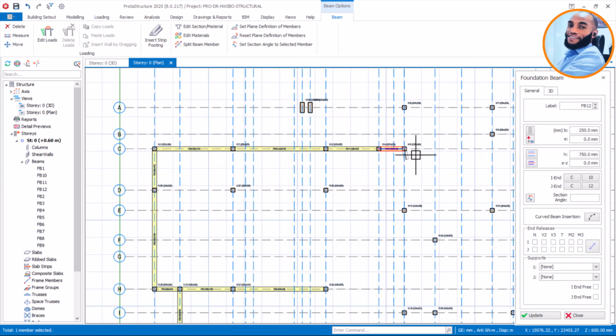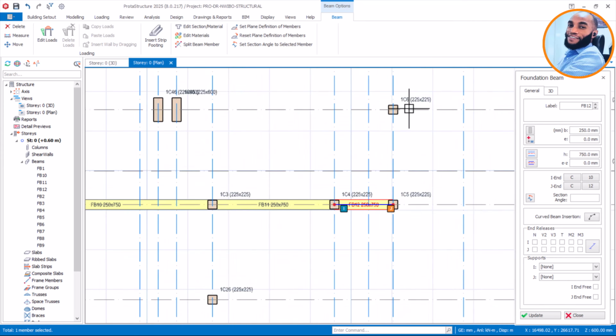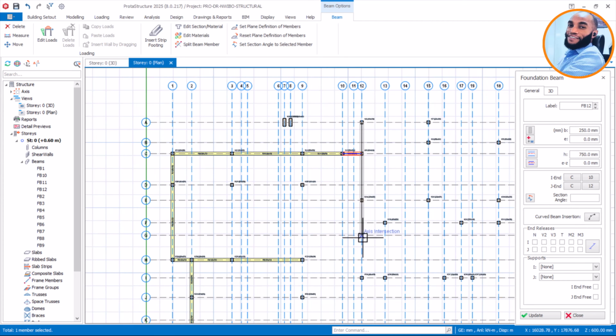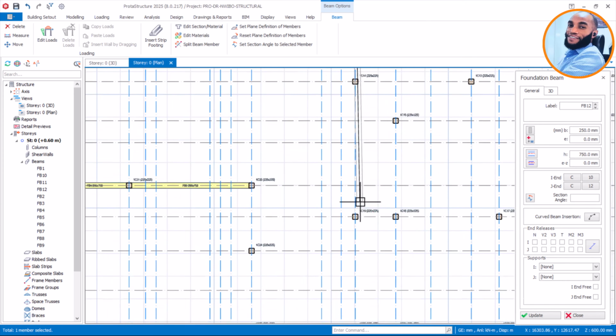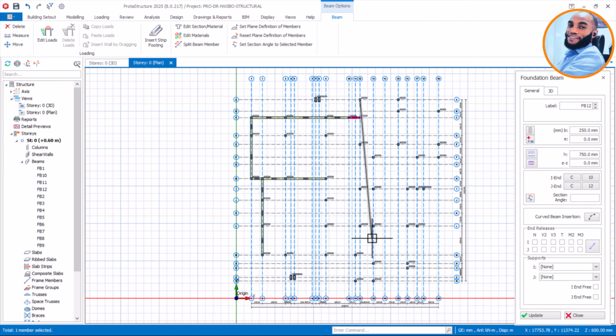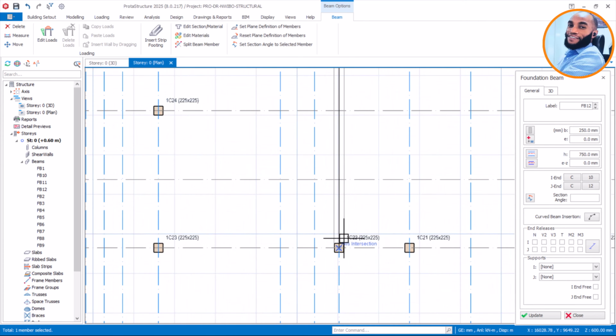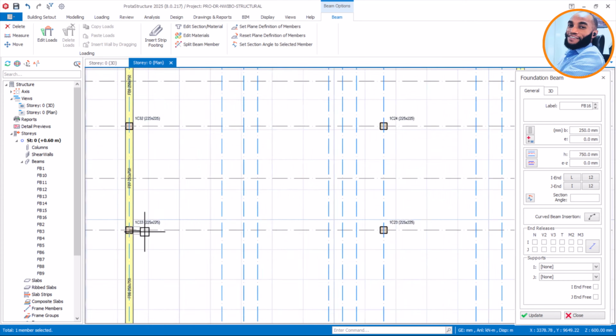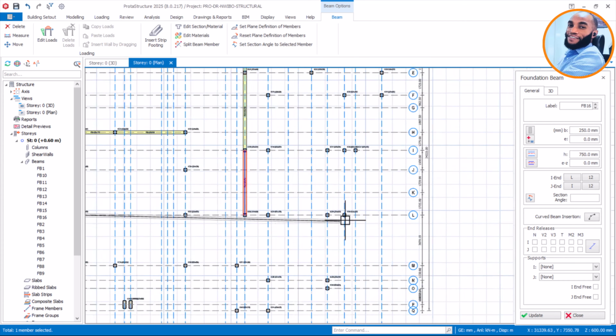Okay, that is fine. All other non-major walls, for example, toilet walls, can sit directly on the DPC slab after we have done our damp proof course. So in this case, I'll continue and click here. Knowing that principle should guide you on how to insert your wide strip foundation beam or ground beams.